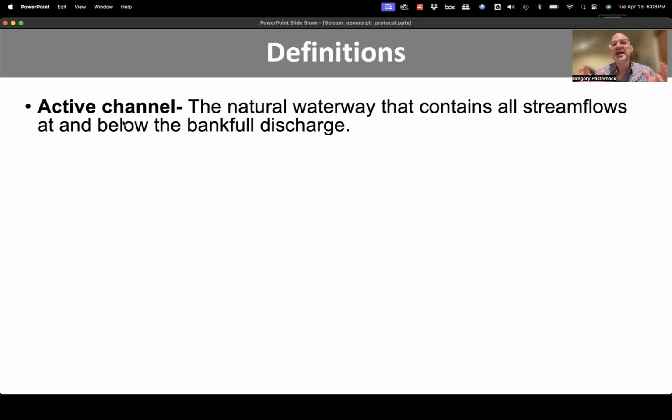So where you see active riverbed sediment, which is usually coarse again, if you're in a cobble bedded river, that could be gravel and cobble. At some point, you'll see a transition to maybe mud and grass. And yes, mud is still sediment, but that's no longer likely to be the active channel because it's not the riverbed sediments.